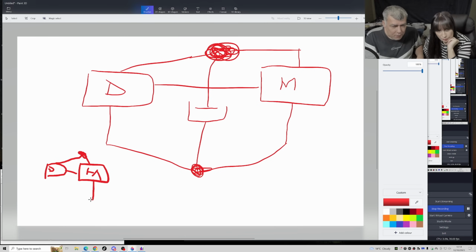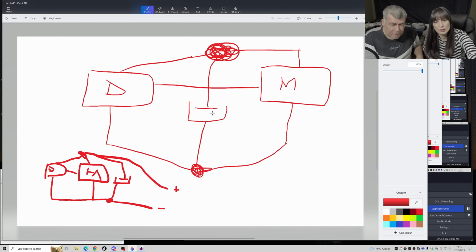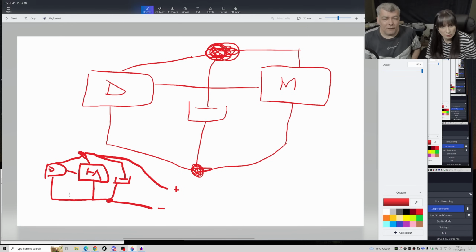Right now, the minus is going here to the driver, and from here, like how you have now, from here you have the capacitor there, and then you come with the power here, plus, and you come with the power here, minus. You can't do it like that. So you have to connect the capacitor like here.